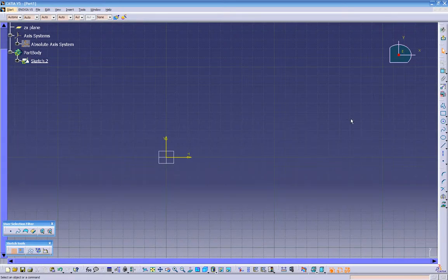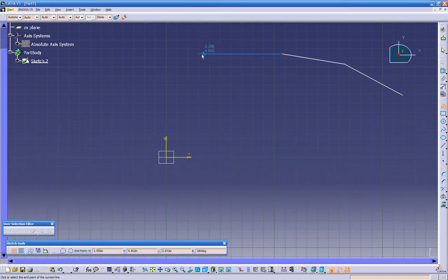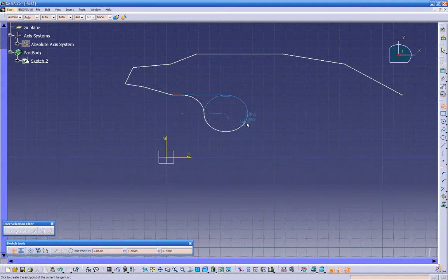So we can create just a quick rectangular. So click on the rectangular. You see we have quite different options over here. We can create a profile. This will create multi-lines. But if you just snap it, you can create a line. But if you snap and hold it, it creates an arc. So snap and hold, then a quick tap goes line, line, line. Then if you hold it and drag it, it creates an arc, the direction you like to go.